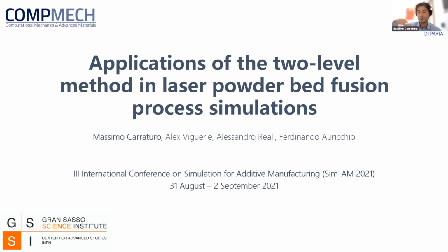Yeah, we have tried to move around the laser. And the solution that we have found is that for a few adjacent layers, you have the melt pool instabilities and rather high temperature gradients. And in this case, we select the local domain large enough to take into account this number of layers. Then at a certain point, the temperature gradients decrease and it somehow stabilizes, the same as we can see for the tail of the temperature solution.